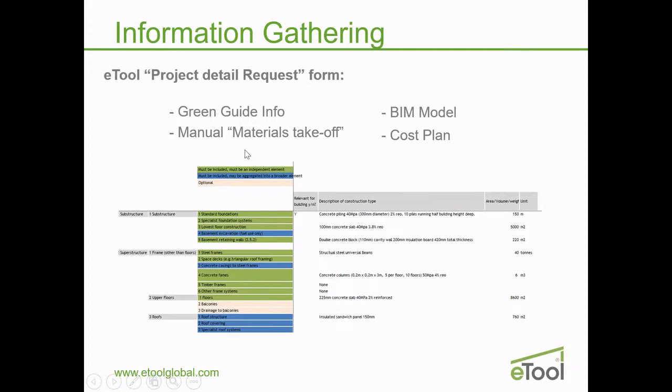You might have a BIM model complete. You might have some drawings where you can manually measure up windows, floors, wall areas, understand what the specs are, and the overall quantities, 150 meters of piling from structural engineer drawings or from the cost plan, 5,000 meters squared of concrete slab from the cost plan or the BIM model. But that level of information will give you an accurate LCA, but it's not available at stage 2, certainly not at early stage 2, which is ideally when we want to be running that first